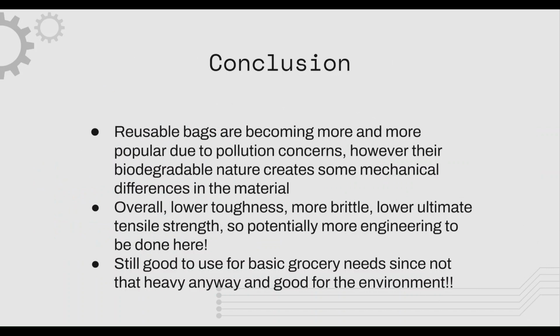And then just to conclude, reusable bags are becoming more and more popular due to pollution concerns. However, their biodegradable nature creates some mechanical differences in the material compared to more traditional non-green polymer materials. Overall, we saw lower toughness, lower ultimate tensile strength. It was more brittle. So there's potentially more engineering to be done here to create a more perfect comparison.